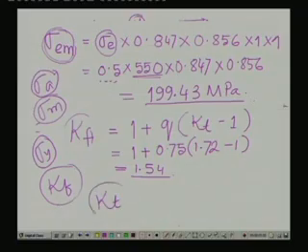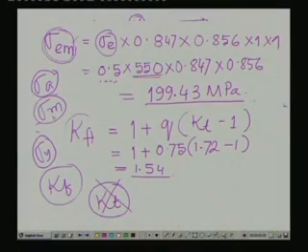Kt is not required because we know that the theoretical stress concentration factor may be neglected in the case of ductile material, because the local yielding will relieve the stress. So, that is the reason ductile materials do not have any Kt in the design calculations. So, we are sure that we know this one, this one, this one, and thereby we can write down the Soderberg criteria to find out the design calculations.